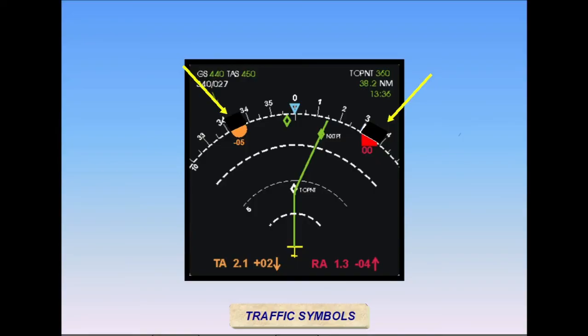If symbols cannot be shown in the arc mode, or because TCAS is temporarily unable to track the contact, the data tag information will be displayed at the bottom of the screen, as shown here. This situation may occur if the antenna is momentarily shielded, or due to a partial system fault. Resolution advisory commands remain valid regardless of the nav display presentation.